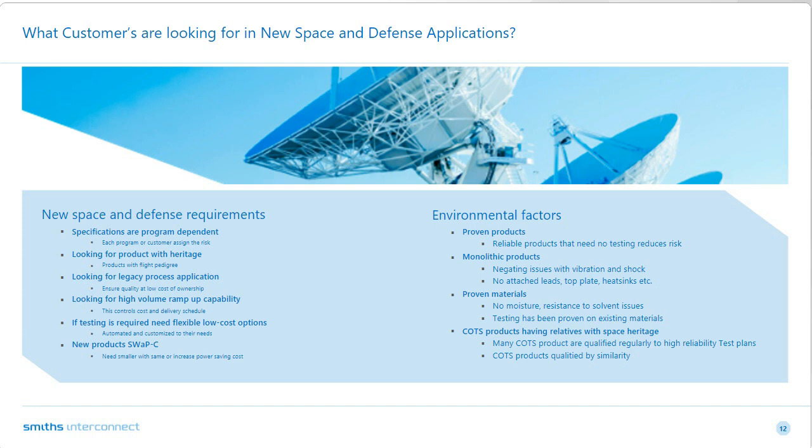Proven materials can sometimes be a difficult deciding factor on products. This eliminates testing like moisture resistance, resistance to solvents, and other test issues because the testing has been proven on these existing materials and manufacturing processes. And the satellites with short life expectancy don't require these additional tests in these areas.